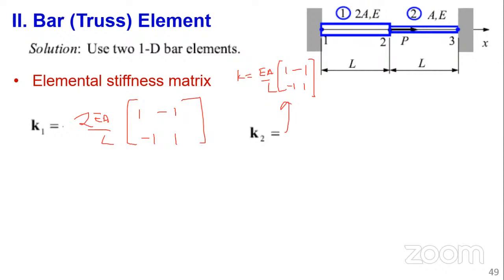Then the next one is you get the global stiffness matrix. So the global stiffness matrix is just the assembly. Remember, I told you you could use this to guide you. Note that the first one, K1, is U1, node 1, node 2. Then K2 is node 2, node 3, node 2, node 3. But I said, when you put this in the stiffness matrix, these are not part of the equation. So if it's in a book you're writing, you could maybe use a faint pencil. This is not part of the matrix.